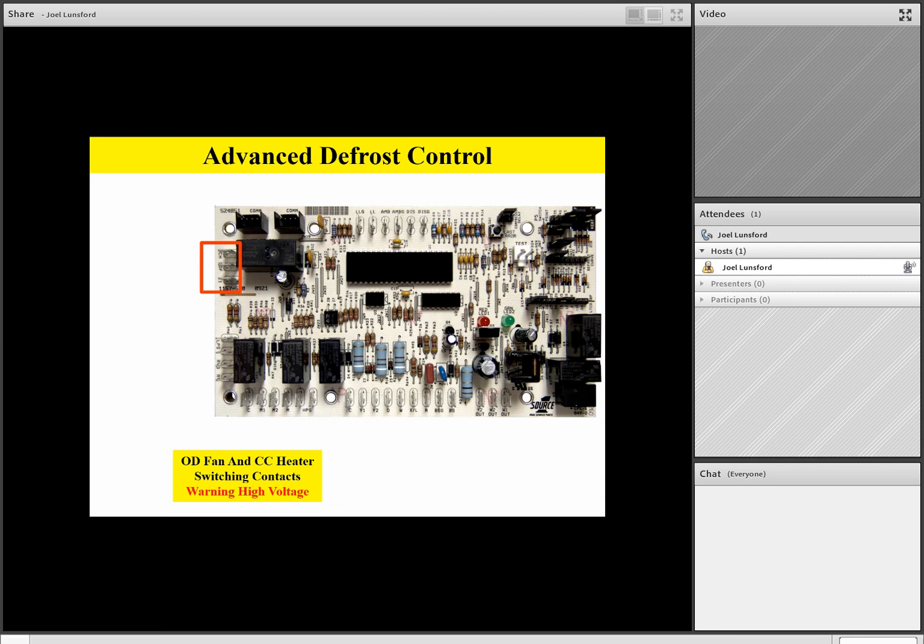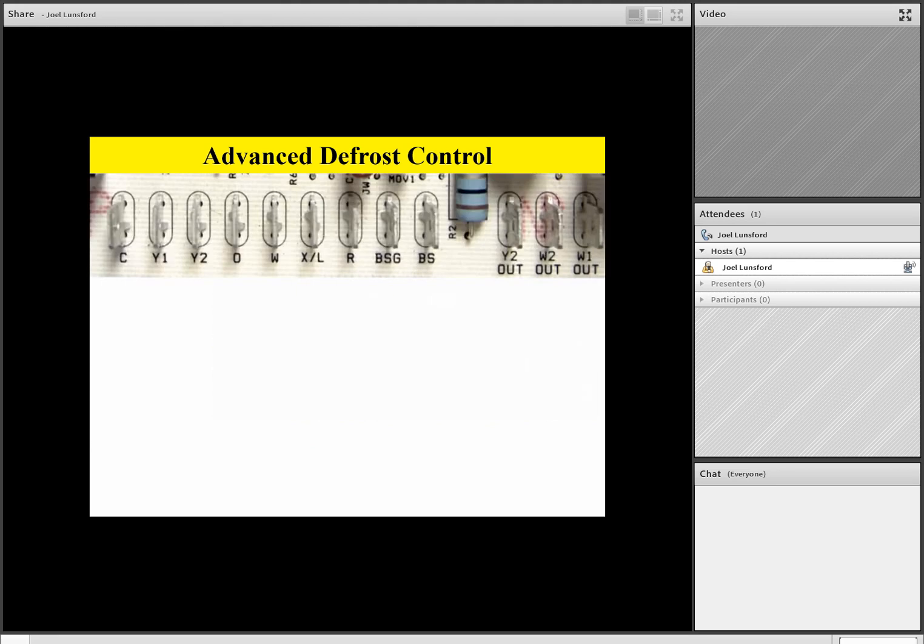So let's take a look at our low voltage wiring. Our low voltage wiring, if we're hooking this board up for a 24 volt, low voltage, conventional thermostat, we will utilize the pigtails. They're normally 6 to 8 inches long, and they'll be colored wires typically. And so the low voltage wiring will have all of these terminals engaged with pigtails on them to wire up with a wire nut and your low voltage wiring for conventional 24 volt wiring.